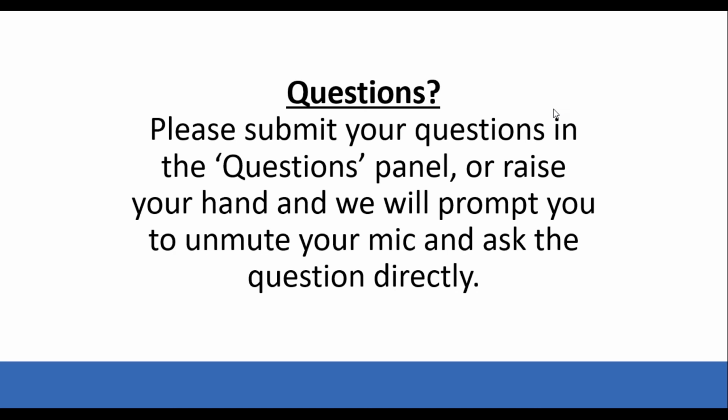But also relative humidity has a variety of effects on indoor air. So it's not only going to affect your adsorbent, so what's meant to remove the VOCs, but as you increase relative humidity or decrease it, the emission rate of VOCs from things like furniture or paints or varnishes is also going to change. So as you change relative humidity, it's not a simple case of a fixed level of VOC. The VOC concentrations will also change.